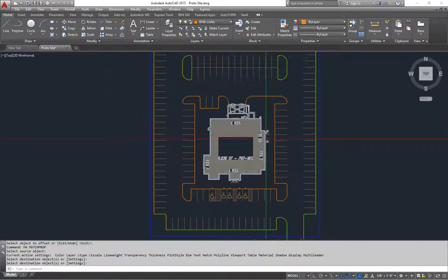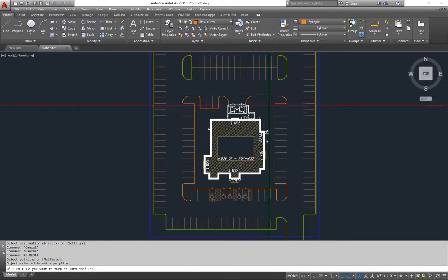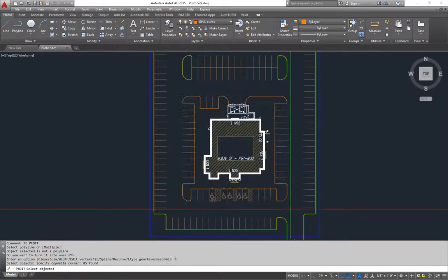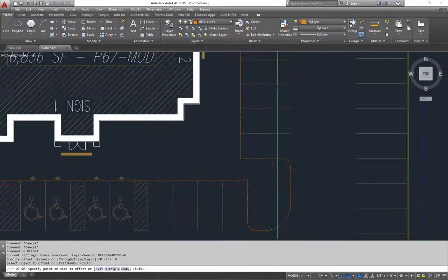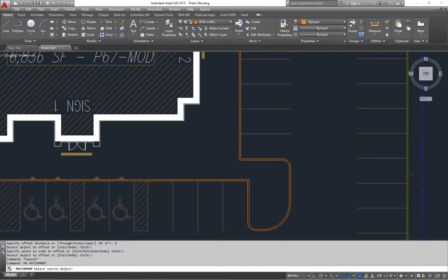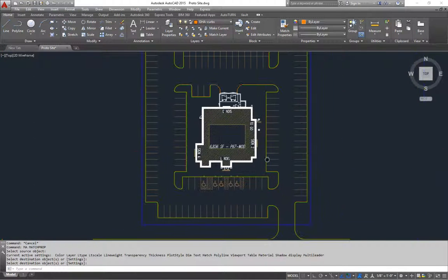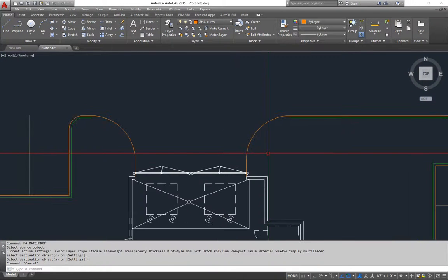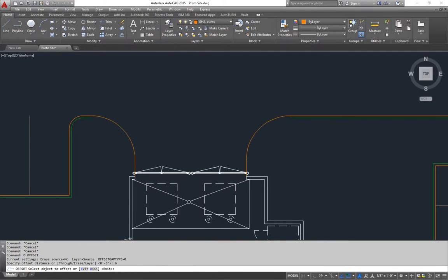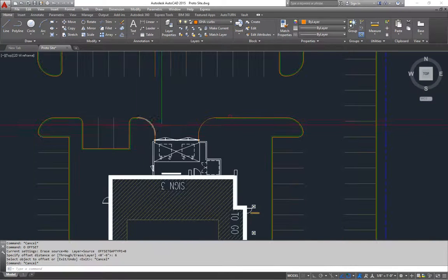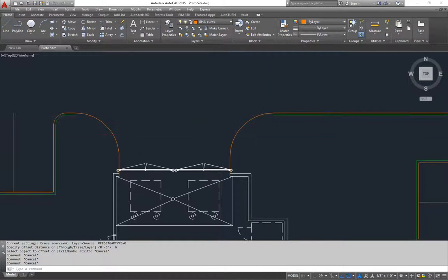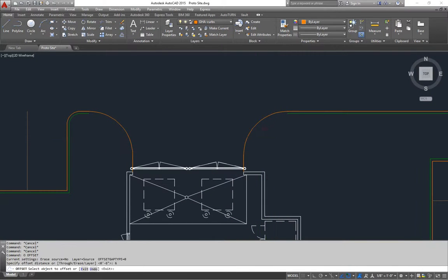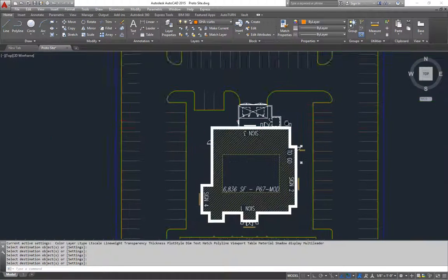And then the only one left now is our pad. P-edit, yes, join, offset 6 inches, and then I'm going to match this curb line over here. Uh-oh, those didn't tie in somehow. Something wasn't clean about these connections right here that's causing them not to work. So I'm just going to go ahead and finish this one out. Sometimes it's not worth going back to make things like that work. So match. I would recommend just doing whatever gets it there the quickest.